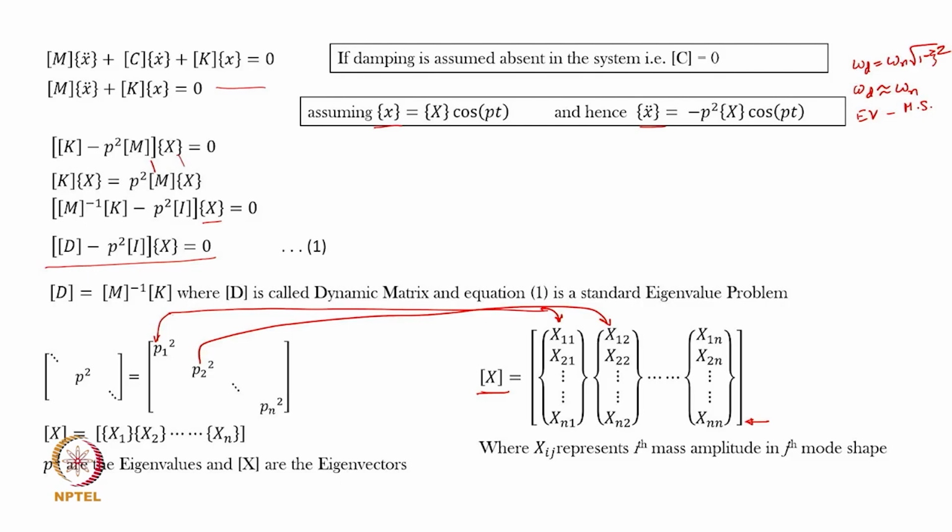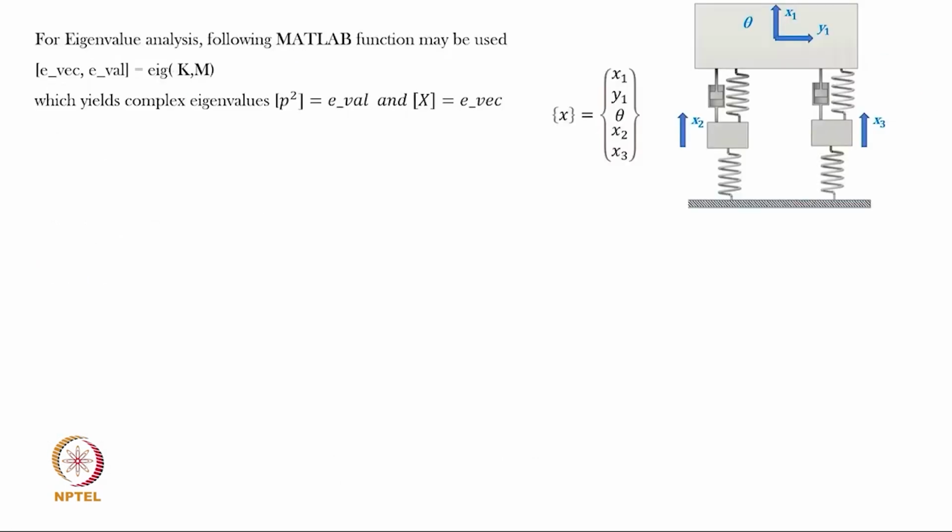So, this is how a multi degree of freedom system gets formulated in terms of a matrix equation. It becomes more appropriate to represent them in the form of matrices, where each individual matrix will have elements depending upon the parameters of the vibratory system, like the masses and the stiffnesses of different elements.